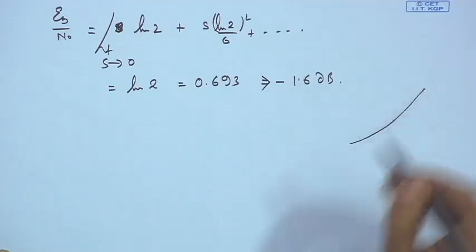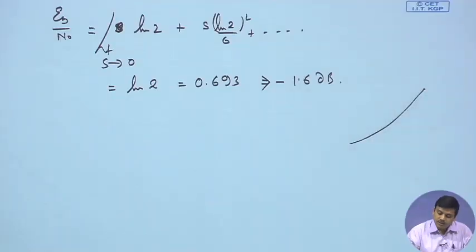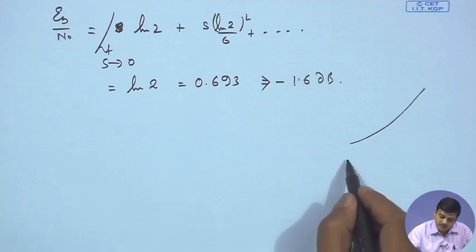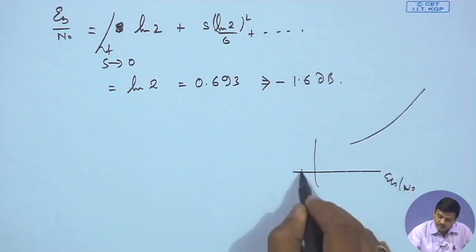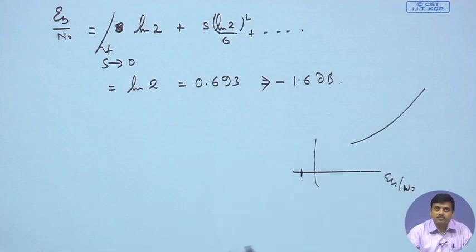So, since we have seen the two situations, one is when we increase the power indefinitely, the capacity keeps on increasing, and if we keep increasing the bandwidth, then we see that there is a lower limit on Eb by N naught, somewhere around minus 1.6 dB is the limit.